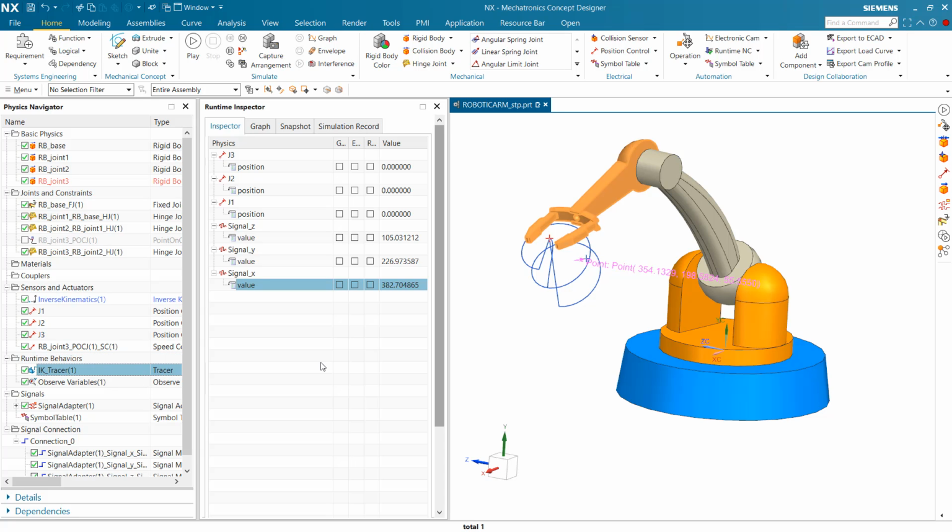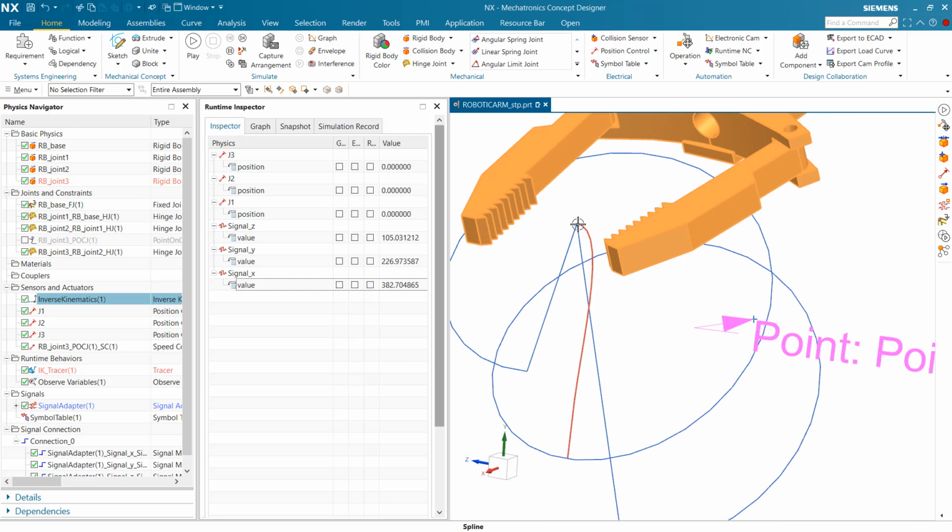So what should be done to hook up with the TCP connections? First of all, I have defined what I want the TCP external signal to do, which is to drive the tool center point. So for example, the tool center point is over here. The TCP external signal will tell me where this point should be at the current time.